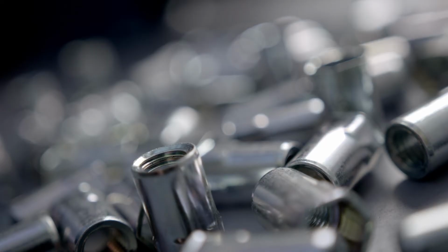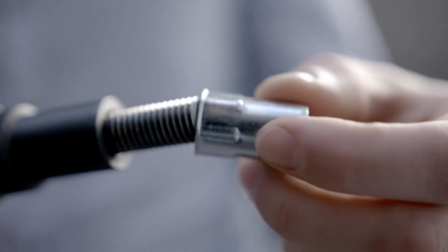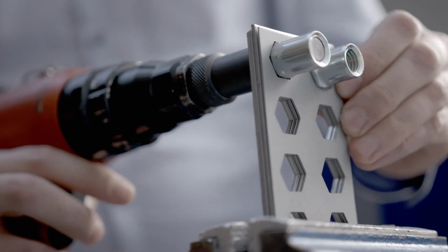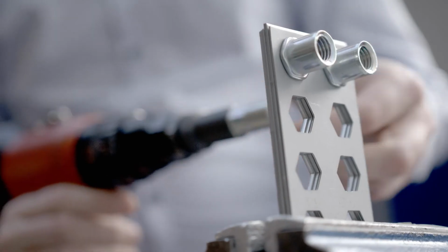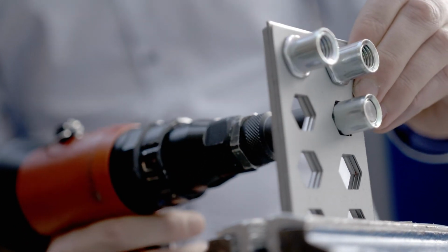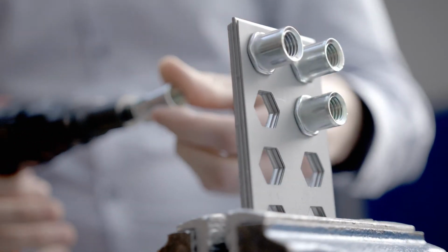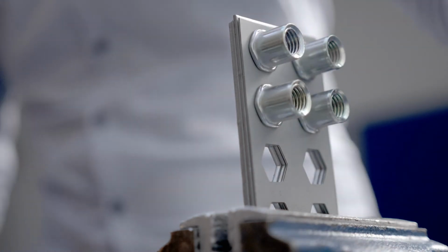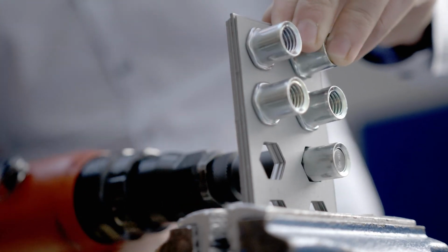Now we are going to leave the world of blind rivets and jump directly into the world of blind rivet nuts. Blind rivet nuts are multifunctional fasteners. At first, they work like a blind rivet because blind rivet nuts are able to fasten 2 or more materials together with only one-sided access. But, and this is the main advantage, blind rivet nuts are used to bring a strong and reliable thread into thin or thick metal plates, profiles, composites or plastics where thread forming is either not possible because the material is too thin, weak, brittle or too hard for thread forming.